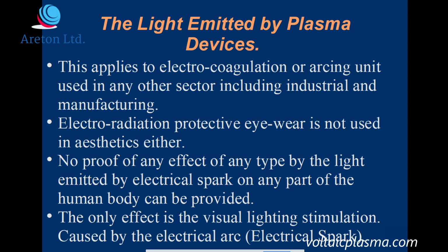I'm not going to talk about them, but one of them is depolarizing the casings before painting them, because sometimes they're polarized, and because of that it's impossible to paint them, and the paint is going to peel off if you don't depolarize the plastic casings. It's got many other applications in textiles and throughout the manufacturing industry. But I'm not going to talk about that.